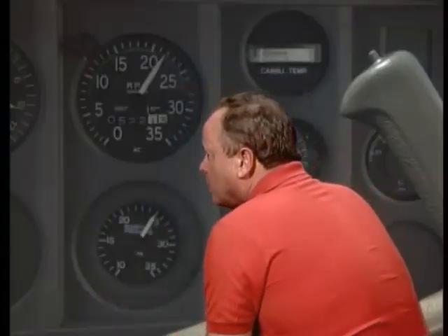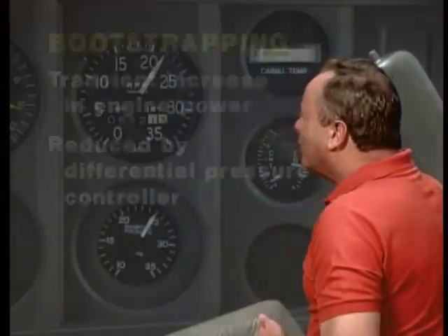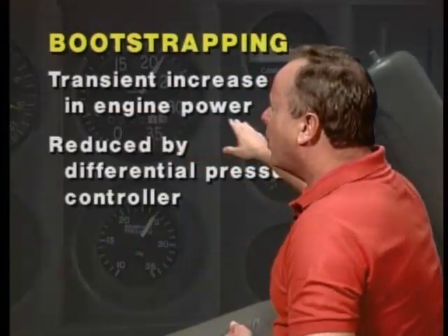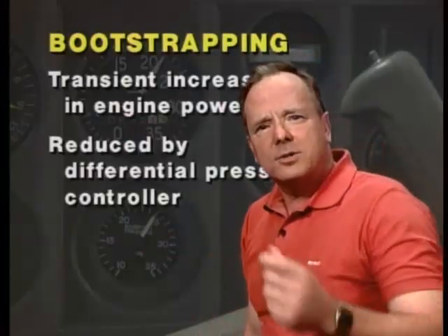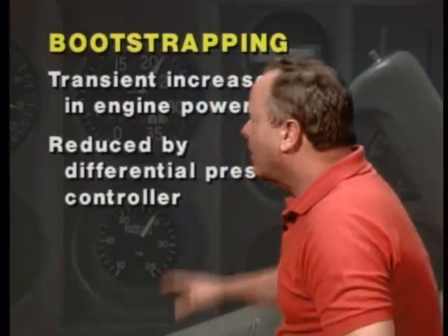That would in turn pump more air into the engine, and that would speed up the turbocharger, and all of a sudden you get what you would call a bootstrapping condition. The FAA refers to it as a transient increase in engine power. And basically the pilot's getting fluctuations or surging that he's not commanding.